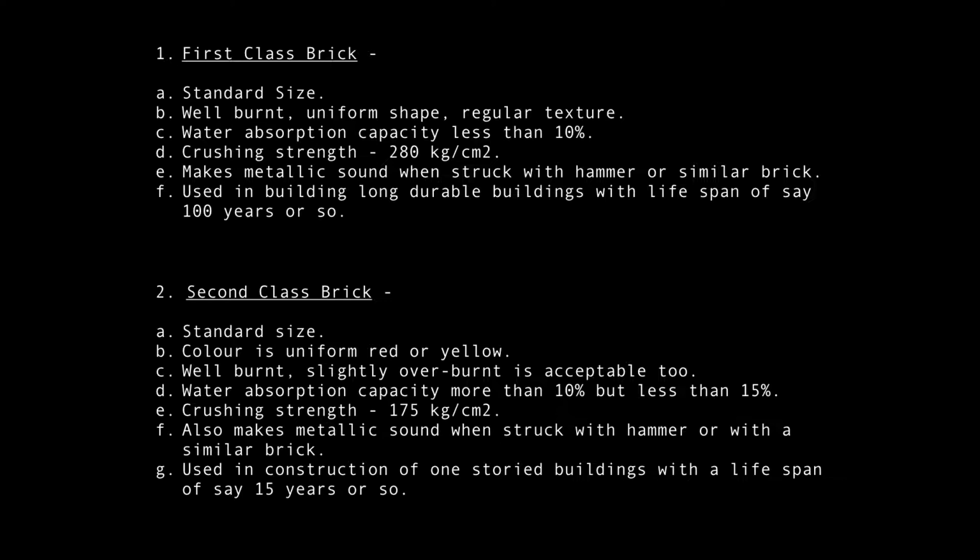Another important point is that if you strike two bricks together, or strike a brick with a hammer, you will hear a metallic sound, which is quite a good test in finding out whether the brick is of good quality or not.